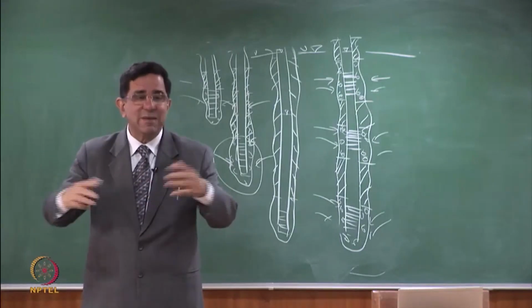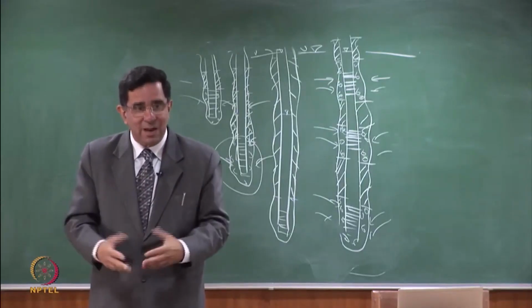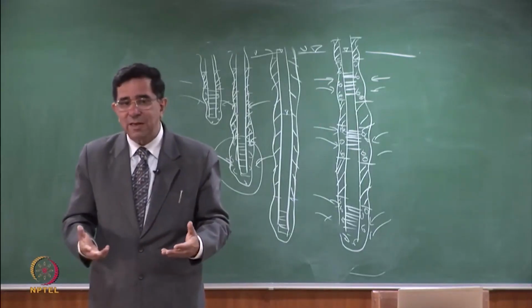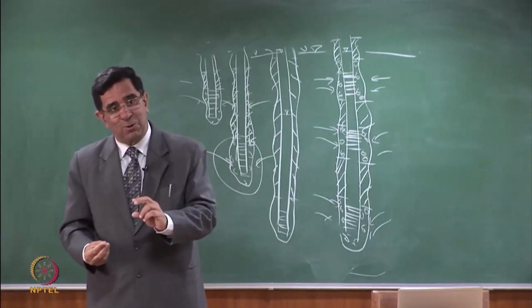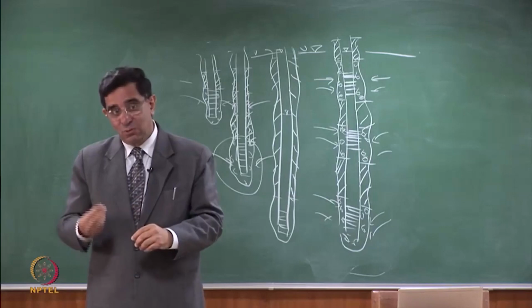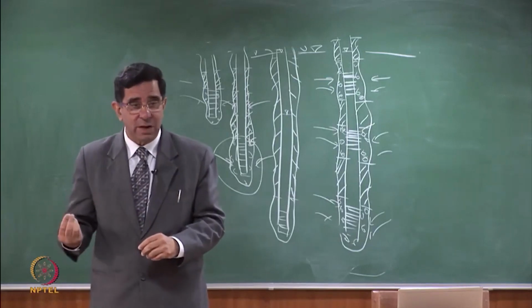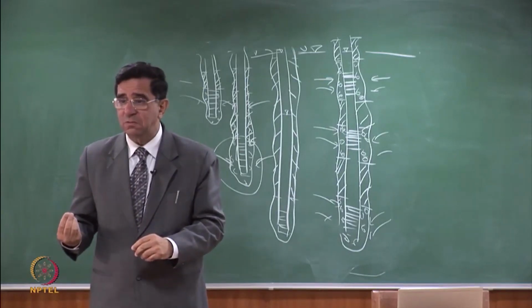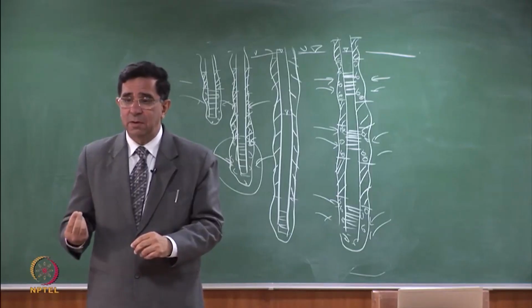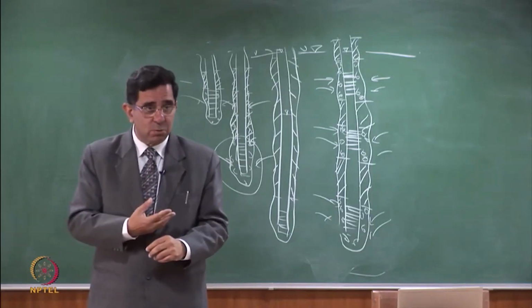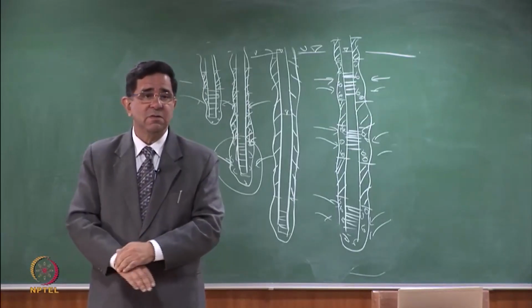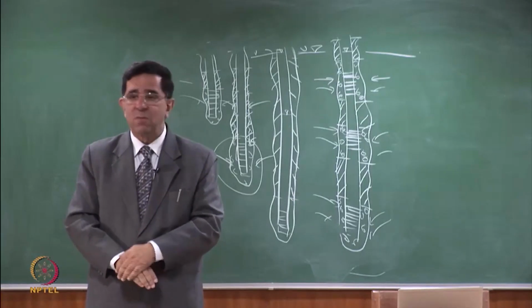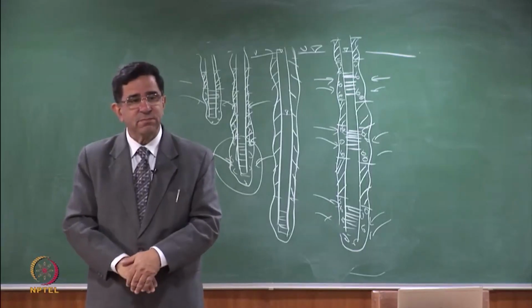Why? You want to maximize the amount of water which can come into the well. So there is not an attempt to find what is the groundwater quality at a particular depth. So you have to make these special monitoring wells where you can get the groundwater samples from that specific depth. So in the next class we'll look at multi-port wells, and we'll look at other devices through which we can monitor the subsurface environment. So any questions?